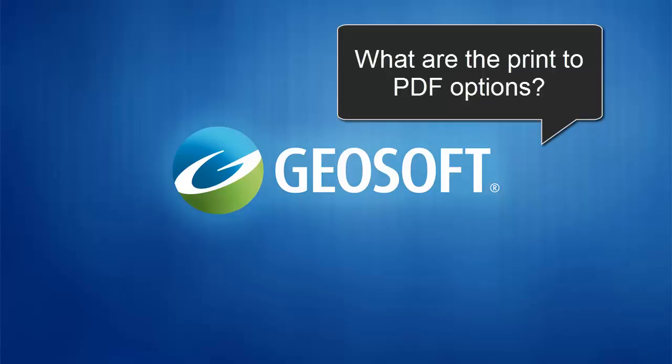Oh, someone asked about plotting to a PDF. Usually the PDF options are under the print capabilities. And there's also an export map option in ArcGIS that you can use to export your layout directly to a PDF. I often use this by turning on and off the layers that I do or don't want to see, and then exporting my layout to a PDF. If there's something else that you're interested in doing, or if this doesn't meet what you're after, just drop us a line and we'll look into that more carefully.